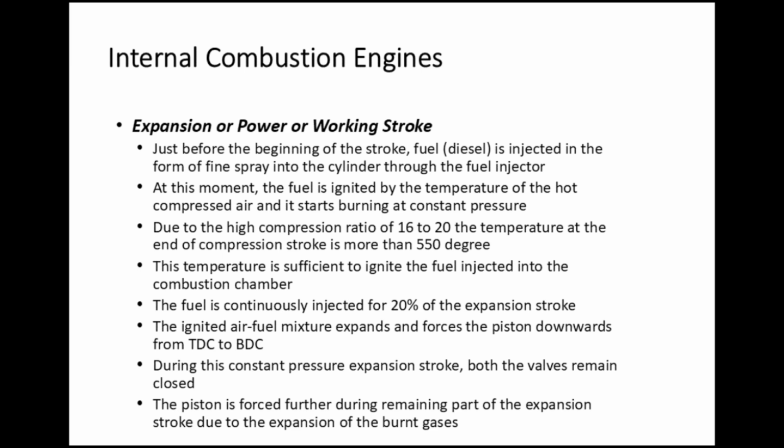The fuel is continuously injected for 20% of the expansion stroke. The ignited air-fuel mixture expands and forces the piston downwards from TDC to BDC. During this constant pressure expansion stroke, both the valves remain closed. The piston is forced further during the remaining part of the expansion stroke due to the expansion of the burnt gases.